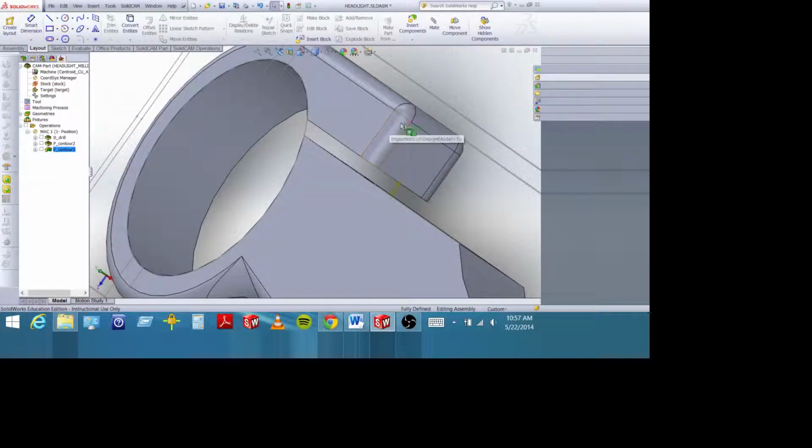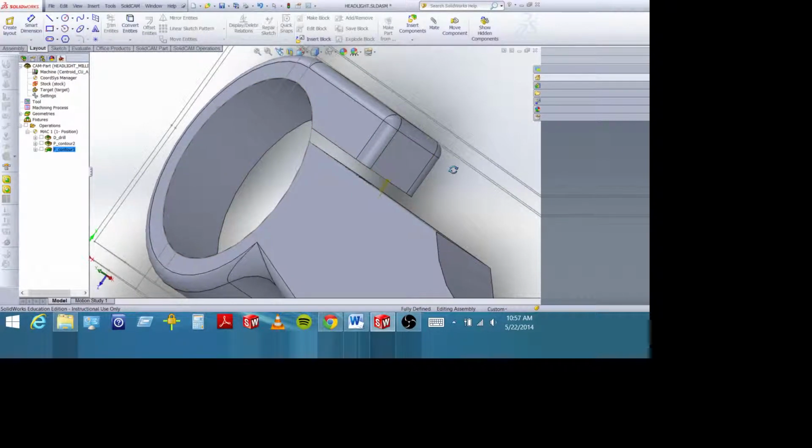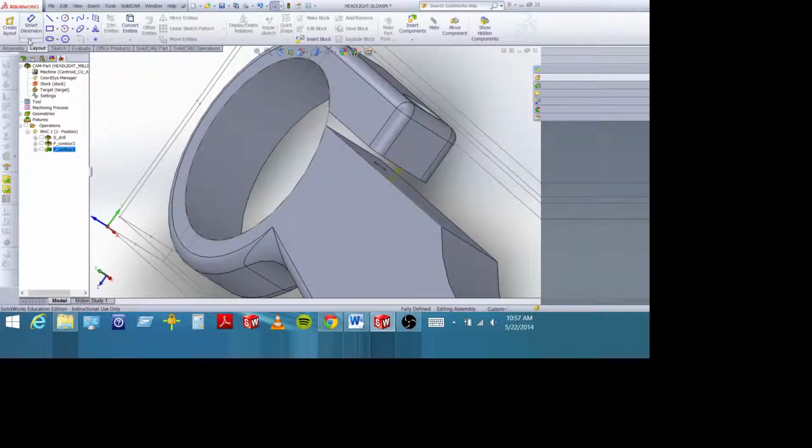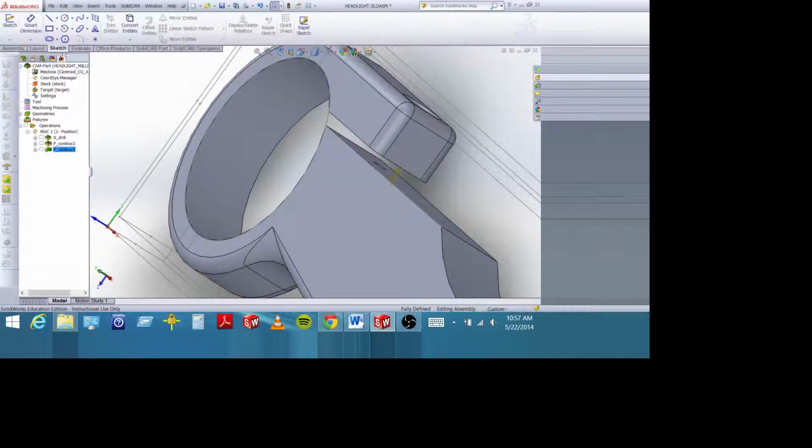Okay. Now there's a couple ways to do it. Notice there's these big fillets, so we couldn't select the geometry up at the top plane. So we selected the geometry at this plane because that line will go all the way around the part. So we're going to select down there. We could draw a plane in on that plane and sketch on that plane, or we can cheat and use 3D sketch. I'm going to go to sketch and go to 3D sketch, which will let me sketch in 3 dimensions without a plane.